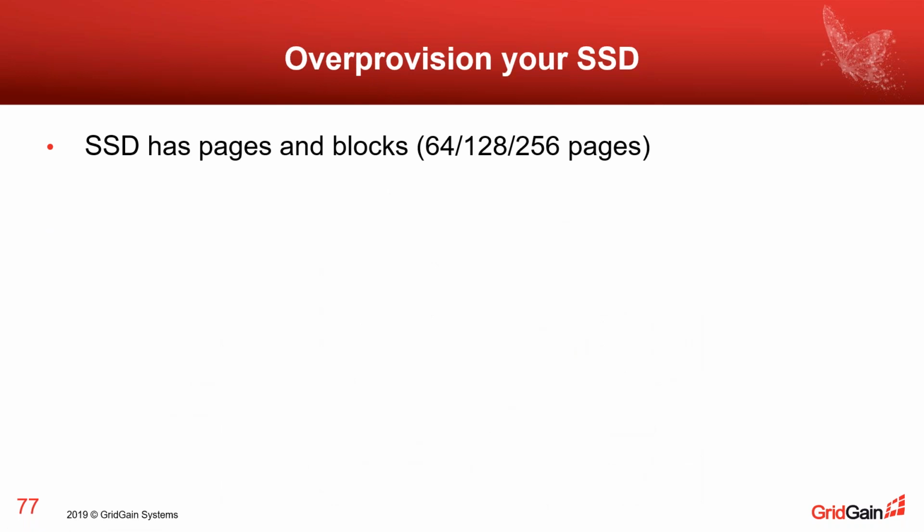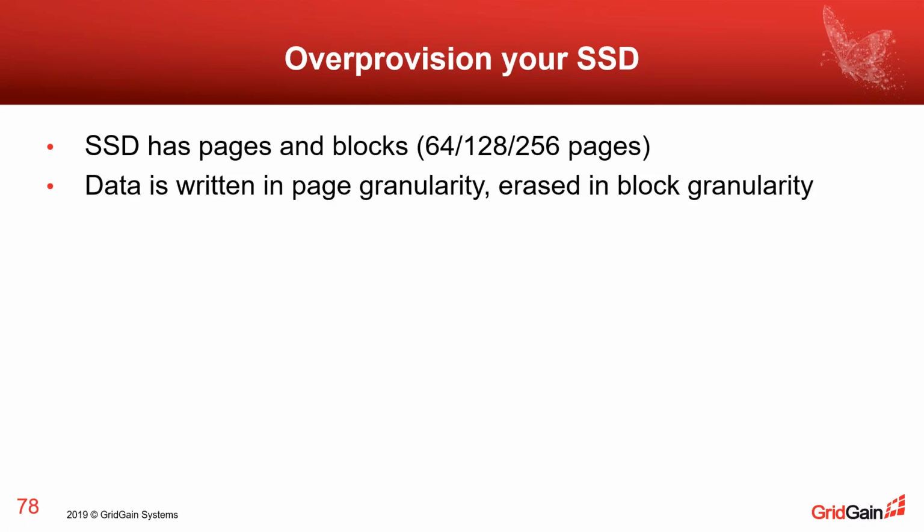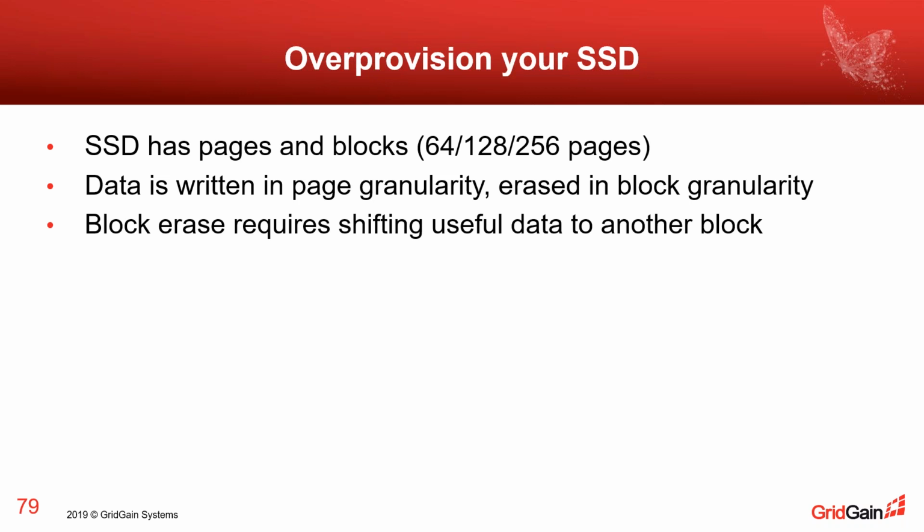SSD drives have pages and blocks. A page is small, for example, 4 kilobytes, and blocks contain a batch of pages, for example, 64. And the difference between them is that data is written in page granularity and erased always in block granularity. And the point is that you can write only to an empty page, and if the page already contains some data, you should erase the whole block in order to make a write possible again. And that's like a physical limitation.